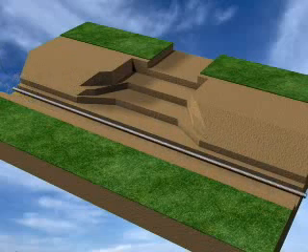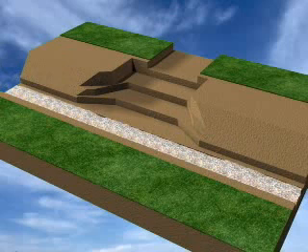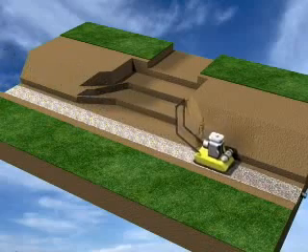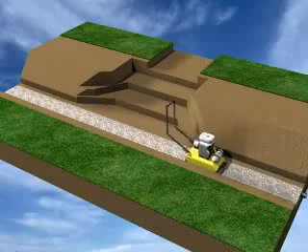Place the drain pipe at the lowest possible point toward the back of the trench that can be vented to daylight every 50 feet. Now that the base trench is ready, place a minimum of 6 inches of wall rock in the base trench and rake smooth. Compact the base, making a minimum of 2 passes.